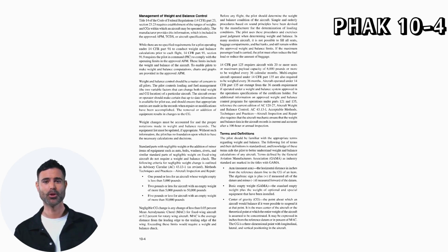The removal or addition of equipment results in changes to the CG. Weight changes must be accounted for, and the proper notations made in weight and balance records. The equipment list must be updated, if appropriate. Without such information, the pilot has no foundation upon which to base the necessary calculations and decisions.